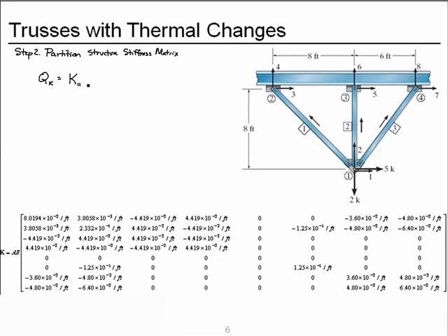a section of the stiffness matrix that we'll call K11, and it refers to forces generated at the degrees of freedom that are unconstrained due to displacements of degrees of freedom that are unconstrained. We'll multiply that by the unknown displacements, which are the unconstrained displacements,